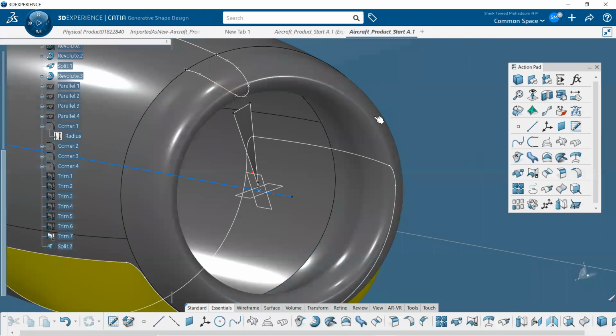For that, I'm going to use the circular pattern option over here. Click on the circular pattern option, then select the blade profile. Then it will ask you for the reference element, with respect to which it can be rotated. I already have a center axis over here. In the reference elements, click on the center axis. Don't change anything. The instances is 17, it's the default. Then it will automatically calculate the angular space between them, then just click.